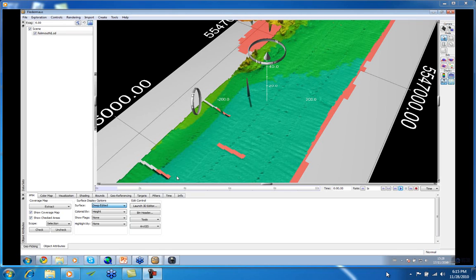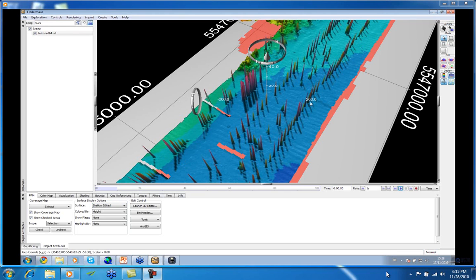And what we do when we want to reject data is we come over here, we go to select mode, or we can use polygon select mode, and over here we've also got an area select mode as well. If you notice, you have an A next to the area, a P next to the polygon select, and an S next to the select mode, and if you hover over the arrow on the explore mode, it's a space.